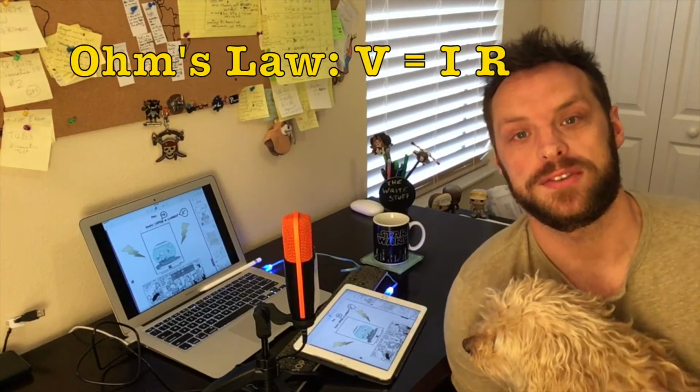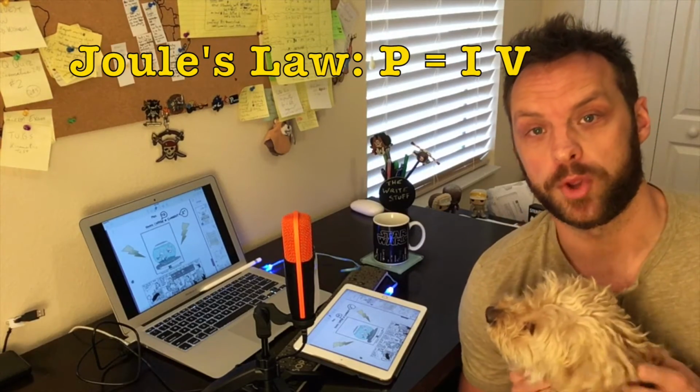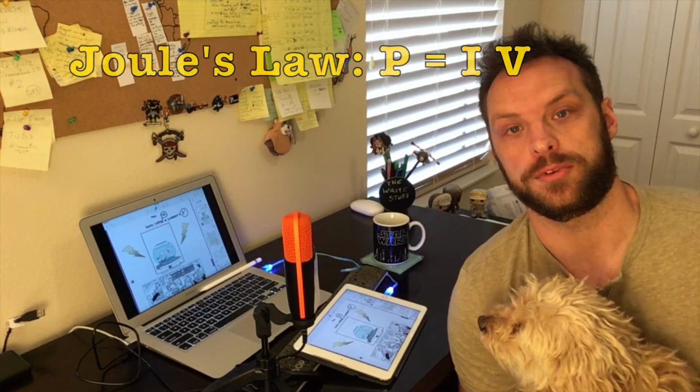The purpose of this video is to help walk you through using some basic math skills with Ohm's law and Joule's law, and maybe even combining them. We're also going to see how to linearize Ohm's law and what that means.